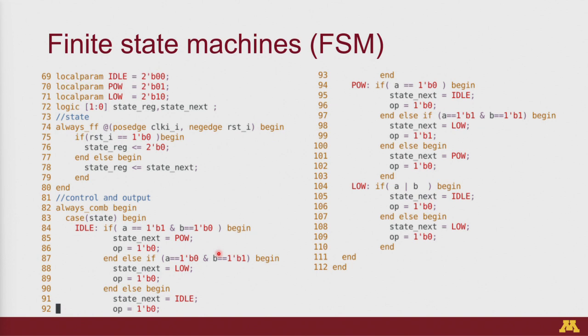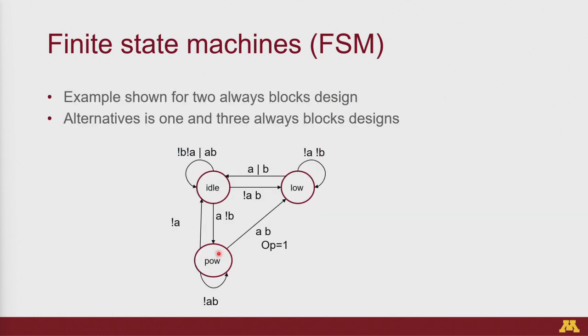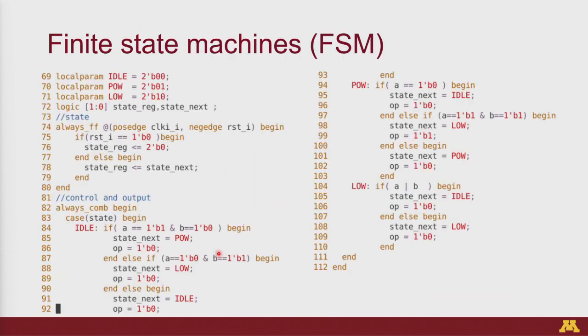What is it, the localparam keyword? Oh, okay, yeah. So the difference between parameter and localparam is that a parameter you can think of as a constant of the block, or like a physical property of the block, which can be overridden from the top. A localparam is the constant or physical characteristic of the block which cannot be overridden.